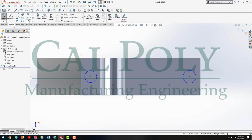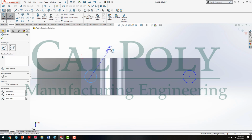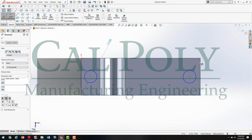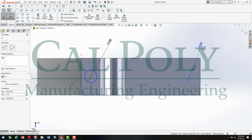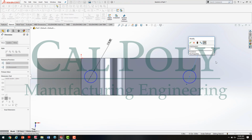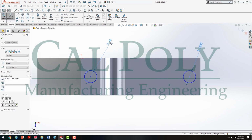So to do that, I'm going to click on smart dimension, and I'm going to first define their size. Their size is 1/2 of an inch. So if I click on the outside edge of the circle, drag up, and key in 0.5, the size changes. Now, I'm going to click on the outside of the other circle, and I'm going to relate this circle size to the first circle. To do that, I can click the dimension, I can write equals, and type in that dimension and press enter.